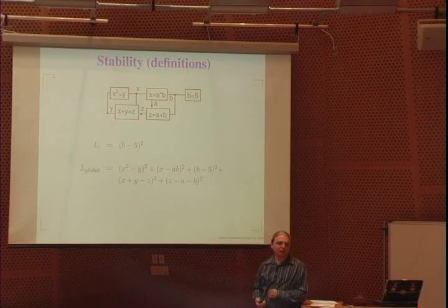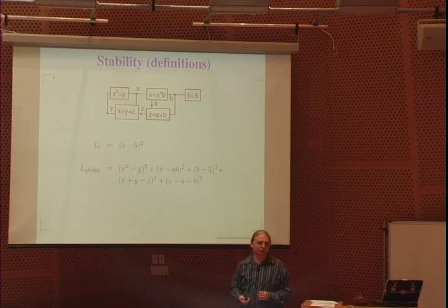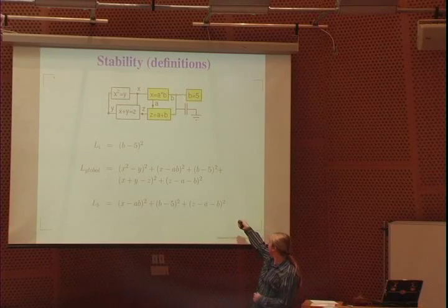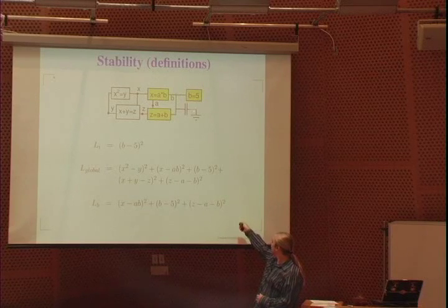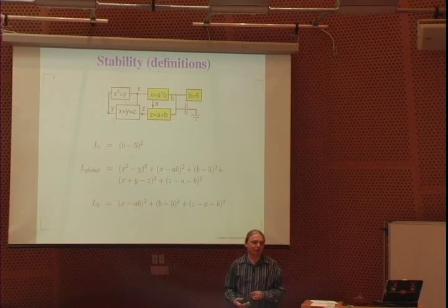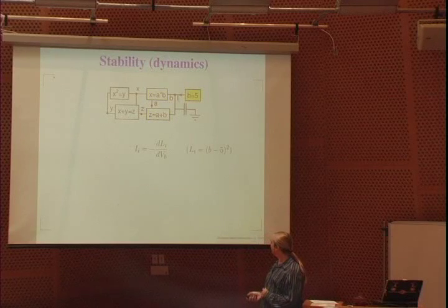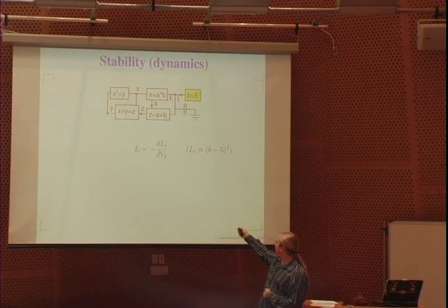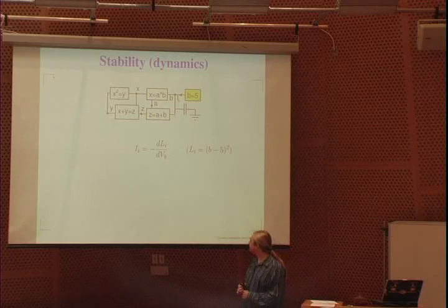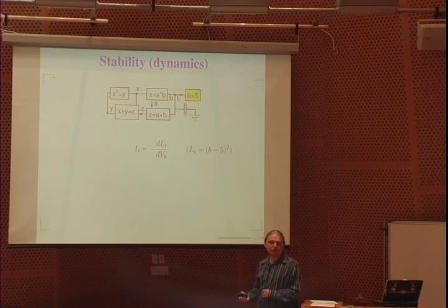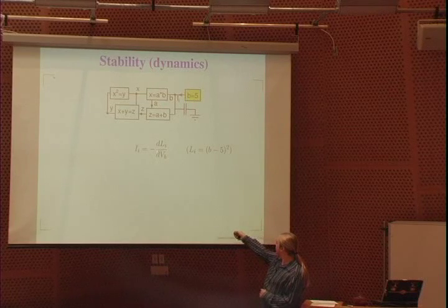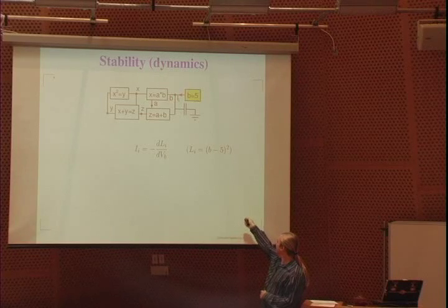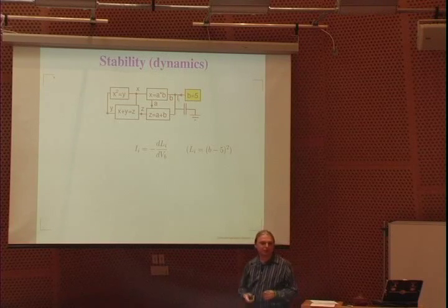And in addition, I'll define the objective function around a node. So if I take the node B, that's just the sum of the objective functions of the constraint blocks around that node. Now, if I look at this, and I look at the current that's being output onto a given node, that current, by the methodology, from a single block, is minus dL_i/dV_B, how the voltage on B affects this constraint.